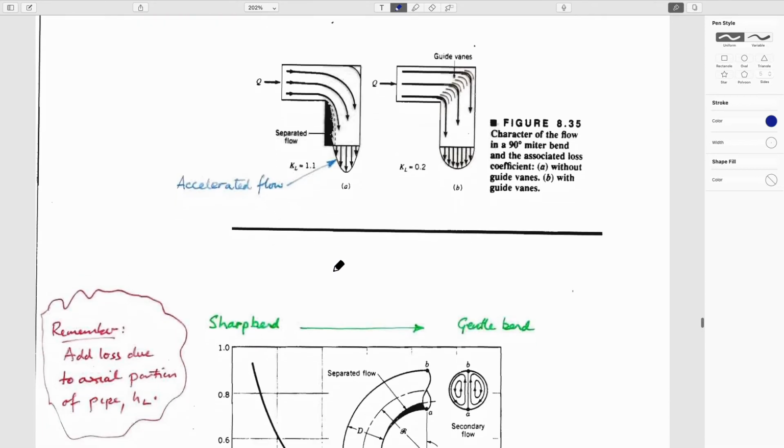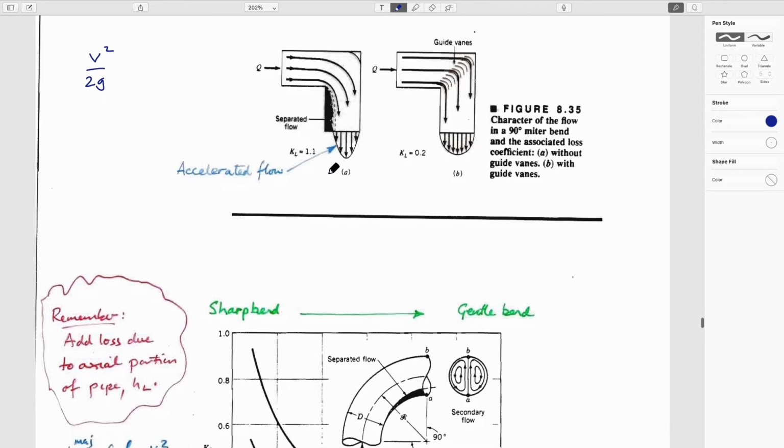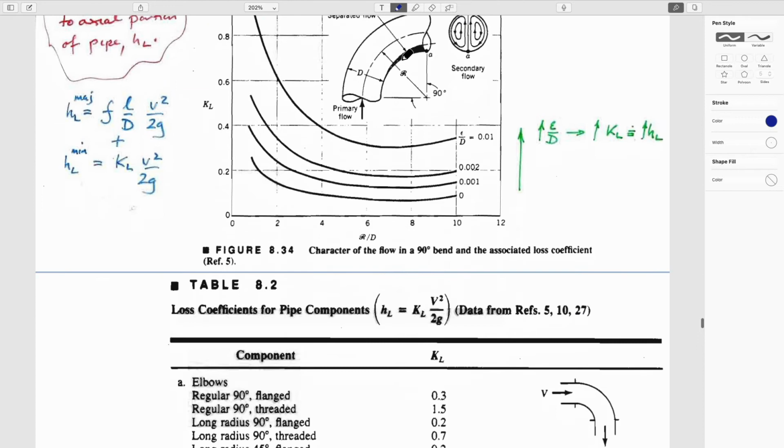The other loss coefficients would be, so the acceleration, v squared over 2g, you think of this as being a constant velocity around here because the flow rate is constant, but of course velocity is equal to both speed and direction. And so if it's changing direction, as in going around a corner, then you have to apply extra force to be able to get over inertia. And so going around bends has some influence as well.